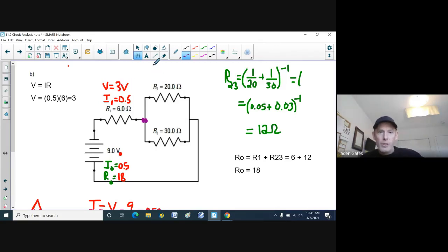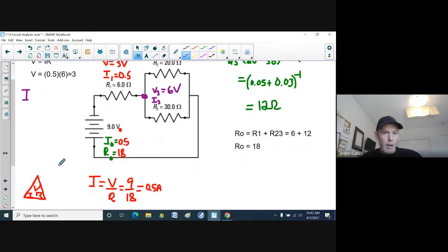So that means V2, you have to use 6 volts down this path. And V3, you got to use 6 volts down this path. All right, because no matter which path the charges go through in the entire circuit, they got to use up 9 volts. Now look at, we have V and R for both of these circuits. So I'm going to use, again, my Ohm's law formula to find the current. All right, because again, current, looking at my triangle, I equals V divided by R.